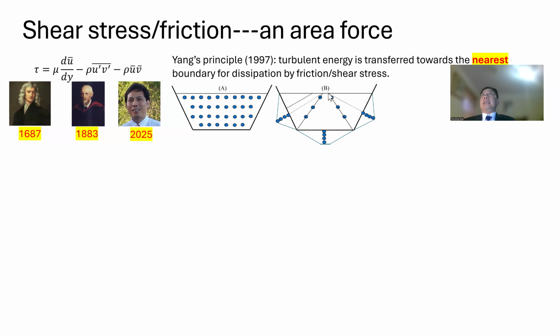This is what we call the division line. If we look through the two normal lines, we can imagine all the students will come to this region, theta P. And if we ask you to determine the boundary shear stress, you will say all the potential energy loss from high elevation, the mountain, to the channel, to the ocean, is converted to the friction force at the boundary here. That means the potential energy loss is this one, divided by theta P is this one.